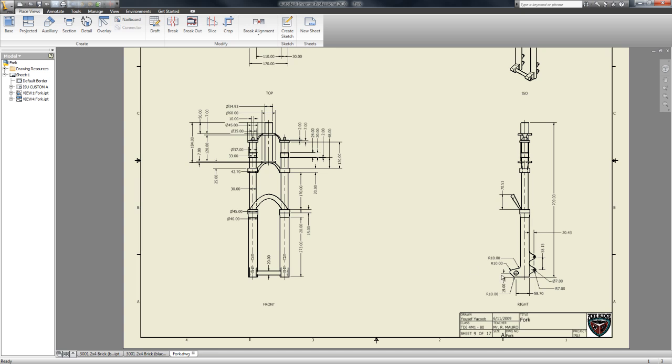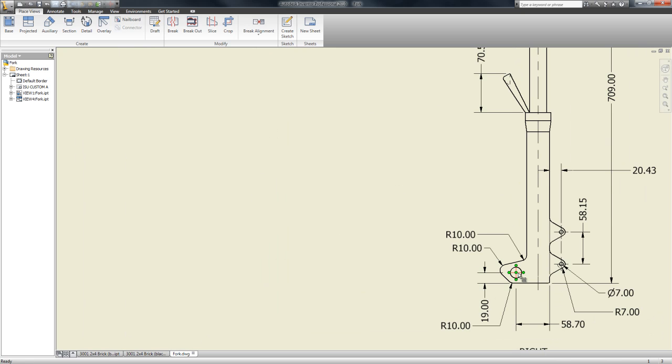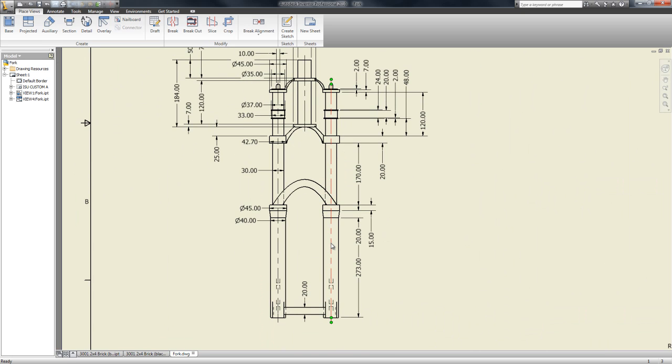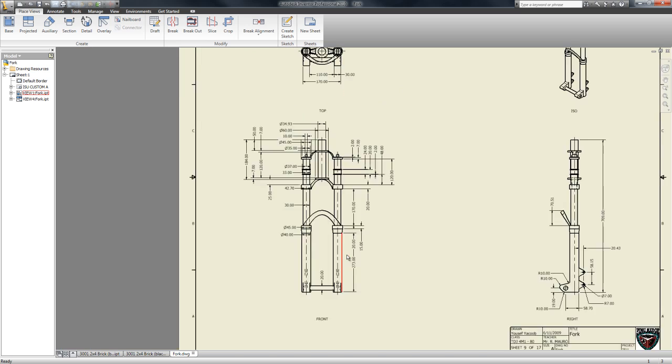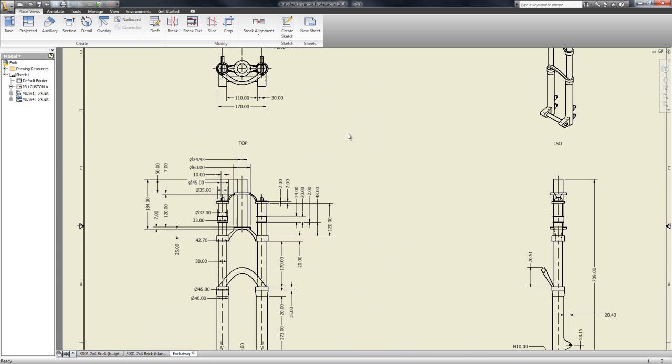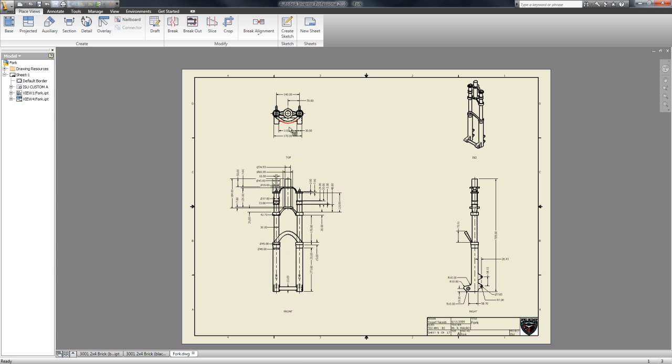Basically, minimize clutter. On all the circles, you're going to want to make center marks. And you can also make dashed lines where appropriate, like down a cylinder. Center marks everywhere again. And you're going to want to keep your hidden lines viewable on the front, top, and right views. I'll go through more tips as we go, but I just want to give you guys an example of a custom title block and some general tips here.